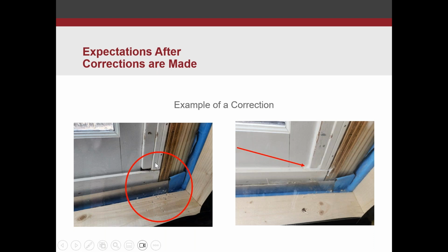And what was happening here was water would run down the vertical trim component inside the unit, and as it fell and passed over this gap, the negative air pressure sucked it in to hit the chamber, and that was an automatic failure.